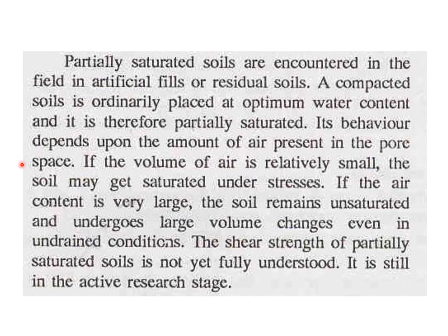If the volume of air is relatively small, the soil may get saturated under stresses. If the air content is very large, the soil remains unsaturated and undergoes large volume changes even in undrained conditions. The shear strength of partially saturated soils is not yet fully understood. It is still in the active research stage.